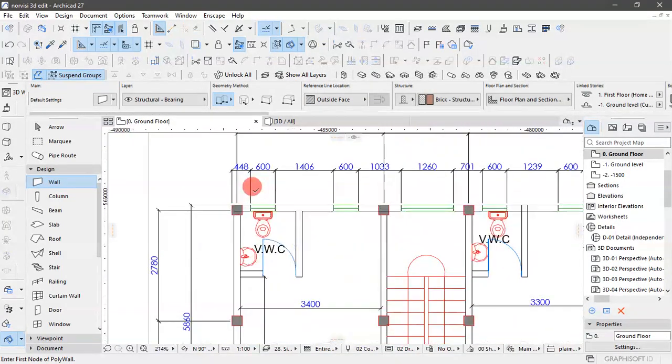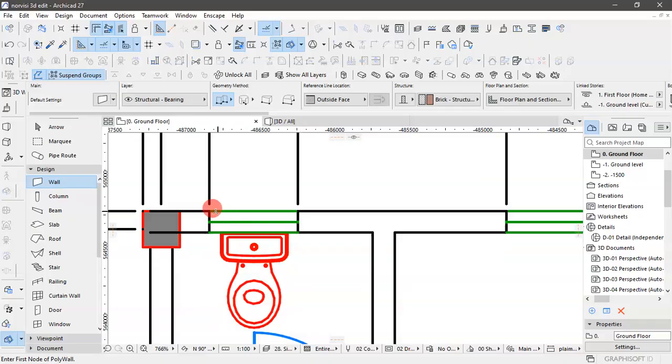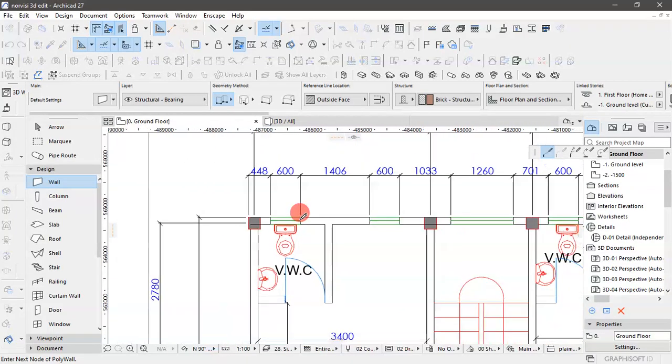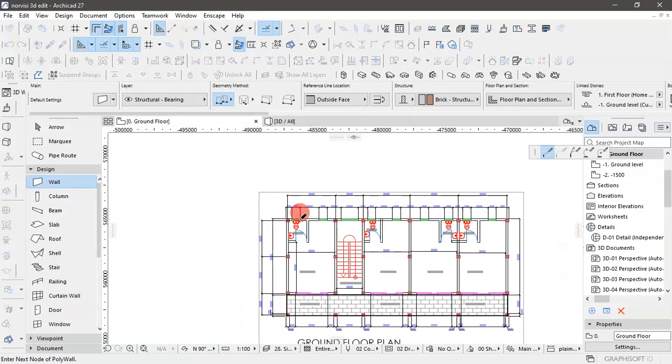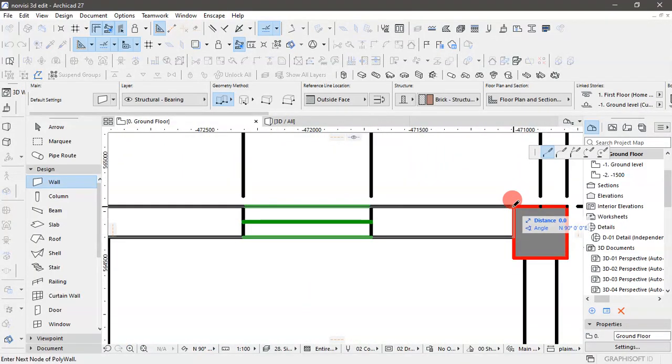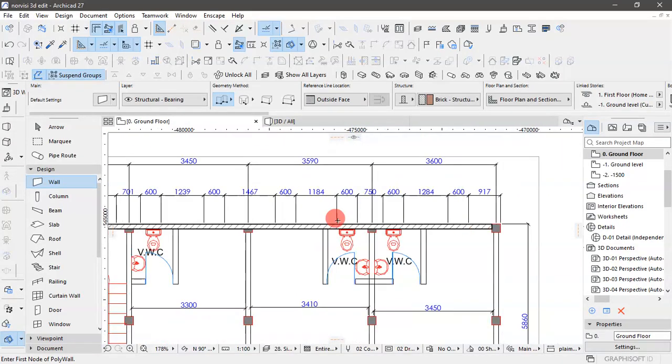Now, I start drawing my wall. Start from a point where I can snap. So select this side and I draw. Now, it's flipped to the other side. To flip it to the right side, just click on P. I'm pressing the key on the keyboard. So now I have this one. Then I draw the extent that I want it to be, which is here. Okay, so I've done my wall.